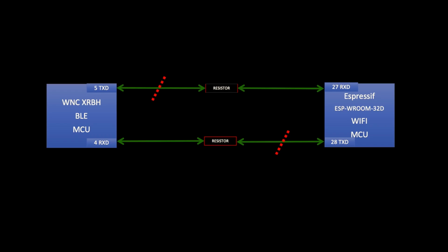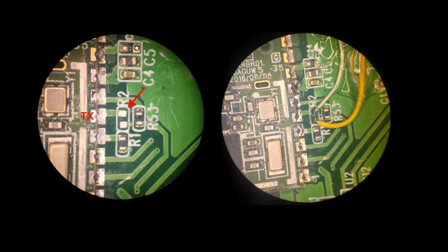So what we want to do, as part of this whole process, since we want to get inter-chip and we want control of inter-chip comms, we need to either tap in, or we need to break the actual circuit runs, and we need to do it on the transmit side on each side of the resistor to make this effective. In this case here, what I did was I just removed the resistor.